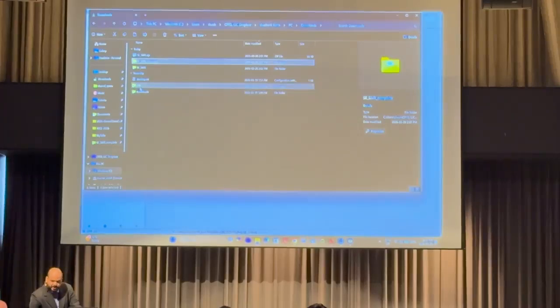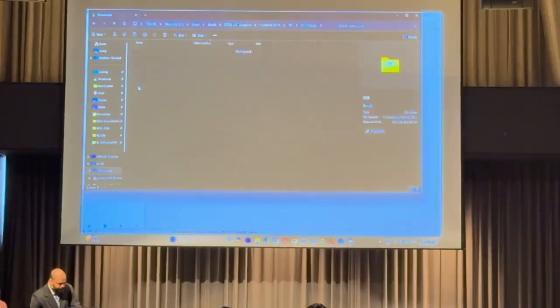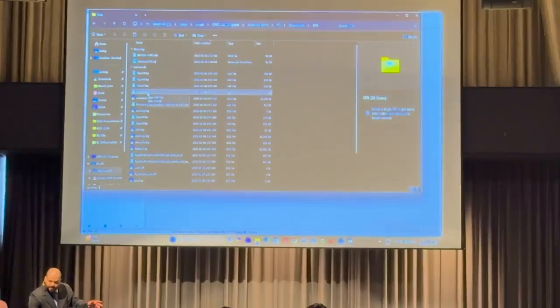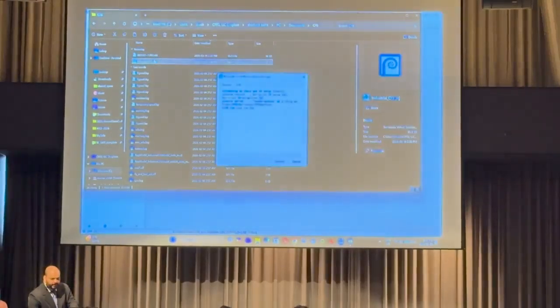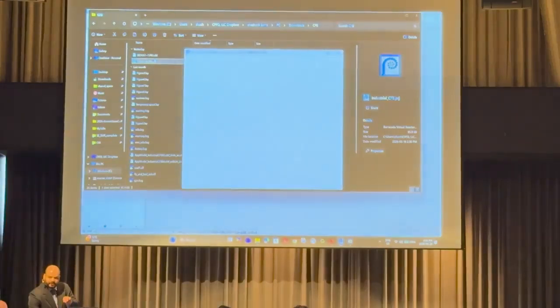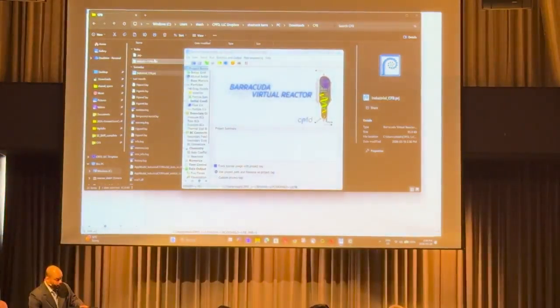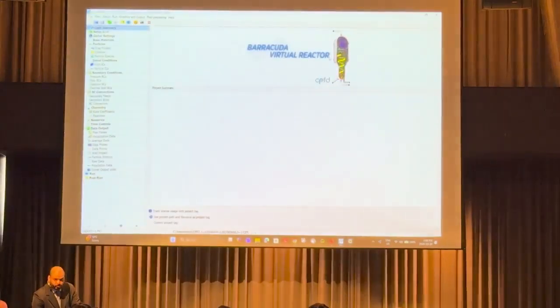But imagine I want to set up a CFD simulation, right? But I want to use, for some reason, some of the reactions that are available in this model. Do I have to manually type every reaction, every rate constant by looking at the post? No, I don't have to do that. In fact, I can directly import all the reactions from one project file or from one simulation into another simulation.